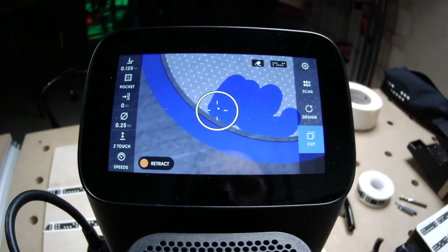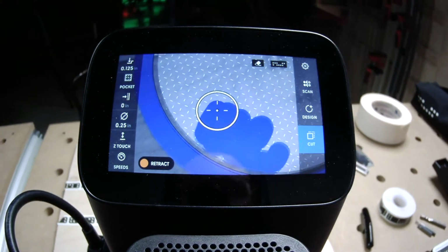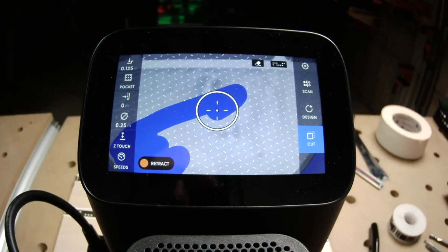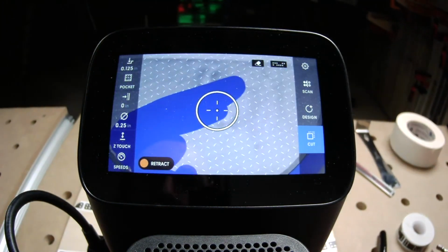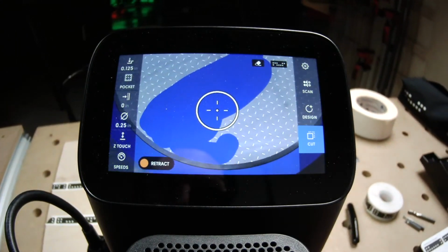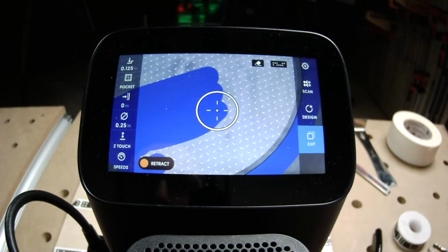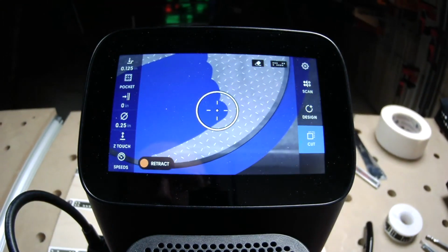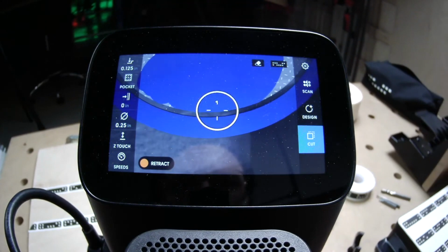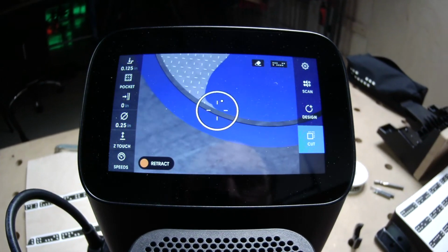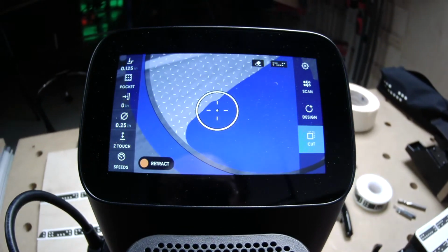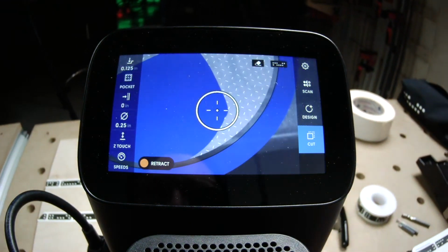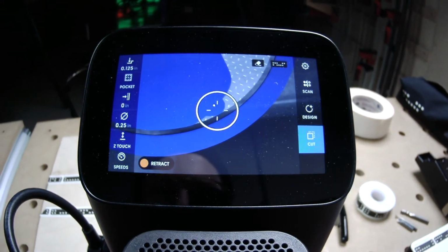Depending on what you're cutting and how deep, there are some things where you're really going to want to work in a counterclockwise or clockwise motion, making sure that the bit is loaded up on the right side. For small projects like this, where you're not going very aggressive, just normal stuff, you can cut back and forth, but note that it's going to feel different going one way to the other. One of my preferred methods is starting in the middle of the pocket and then going clockwise, making the circle bigger and bigger until you finish the shape.